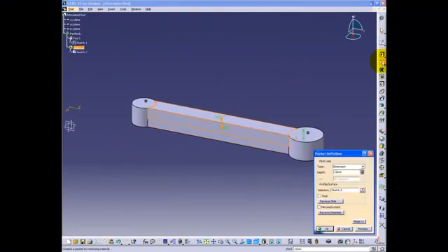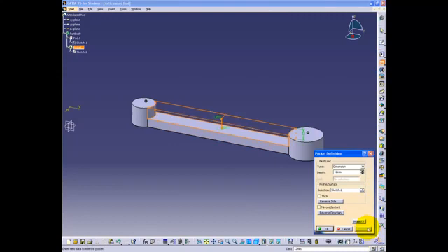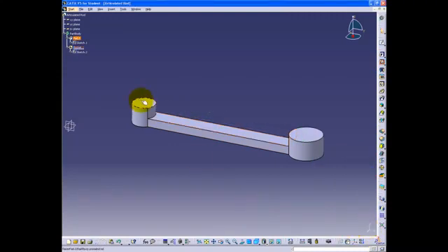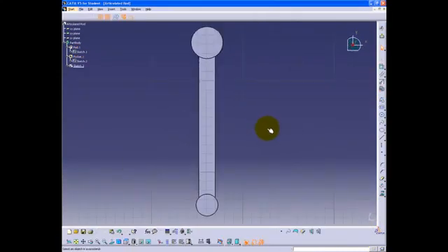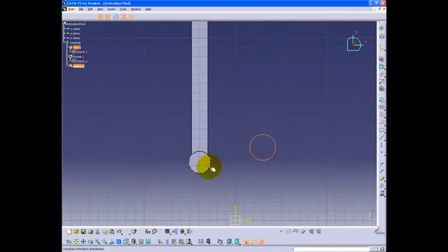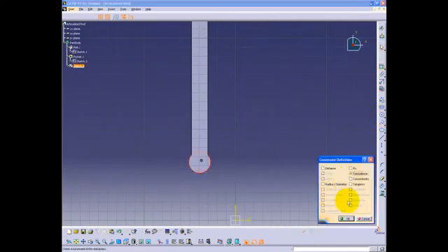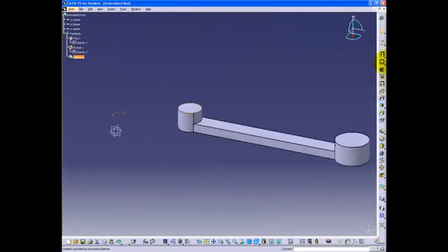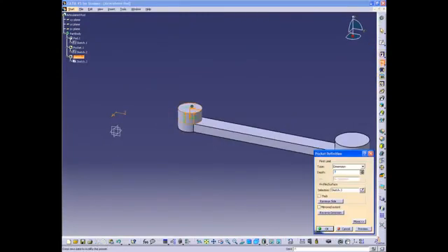Click on the Pocket button. The depth we want to pocket is 12mm. Now, select the top surface of the smaller circle and enter Sketcher. Using the Circle button, create a circle that has coincidence to the padded circle. Exit Sketcher. Again, clicking the Pocket button, pocket 7mm.